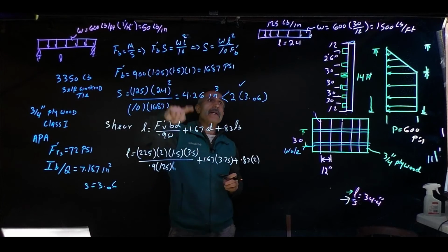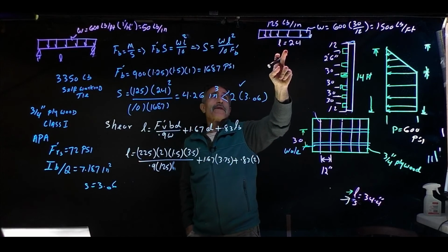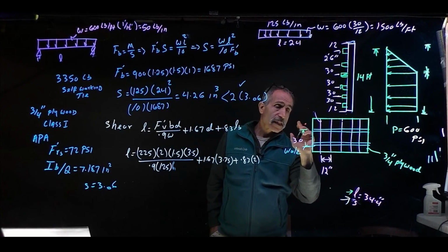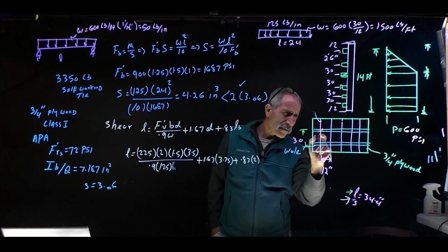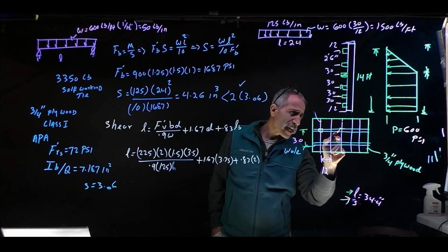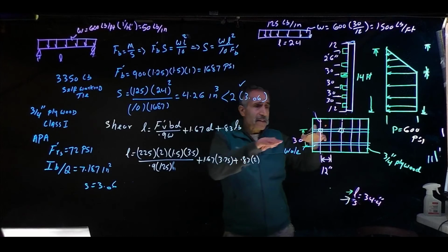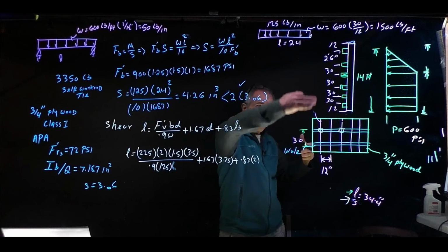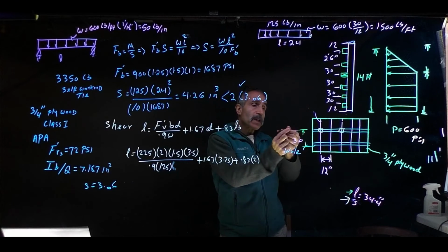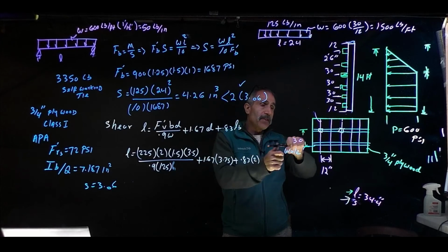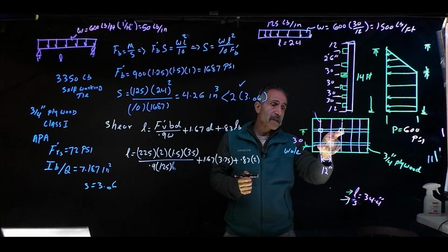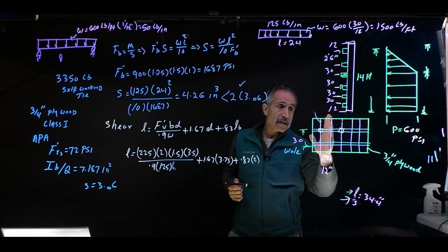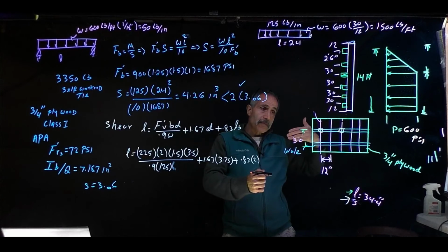I want to go back in here. I didn't explain how we got the length of the whale as about 24 inch. You might think, oh wait a minute, it's 1 foot. It's not 1 foot because of the tie spacing, which is right here. You have a tie right here, and you put a tie right here 24 inch apart, and on the other side you have the same thing, and the tie goes between and locks up here. Therefore your support system is about, your span is going to be 24 inches, because remember, the stud is not supporting; the force is coming this way, coming outside.